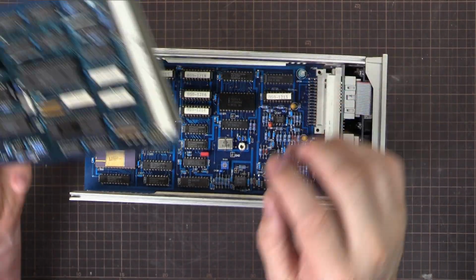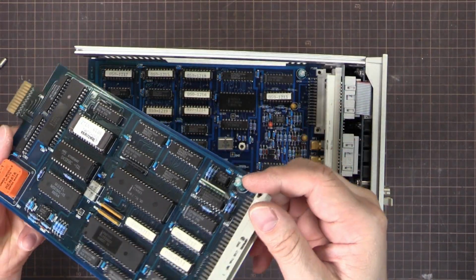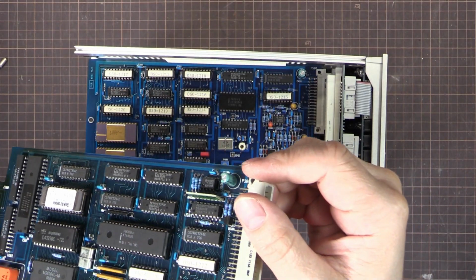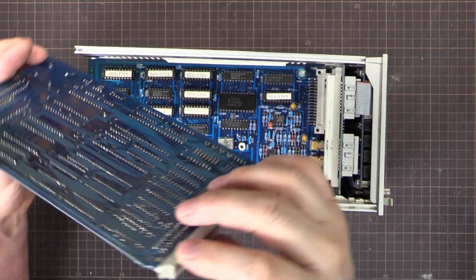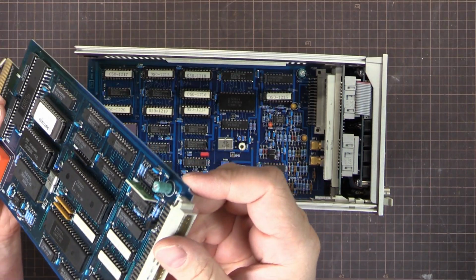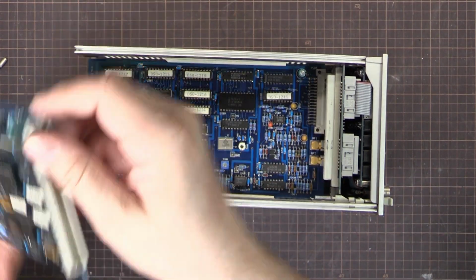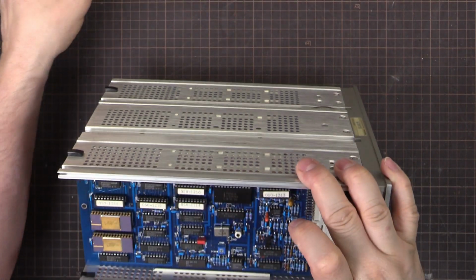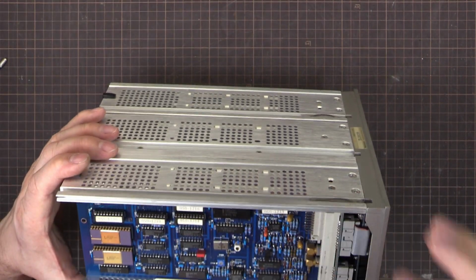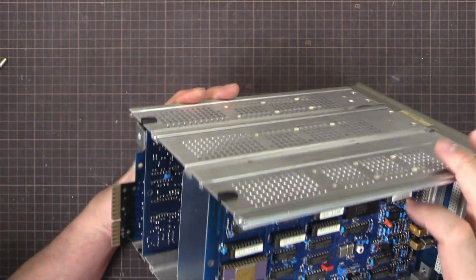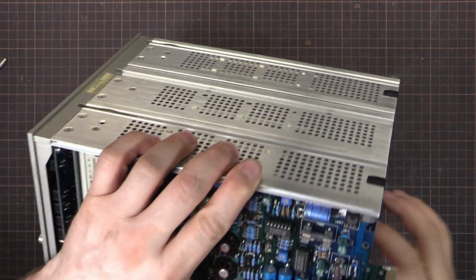There's the electrolytic here. What's that? What brand is that? Towa brand, Towa. Never heard of them. 105. No, that's 85 degrees rated. So maybe I'll pull 1 or 2 and just check it, because I don't want to just go and shotgun all the caps if I don't need to. But they're pretty cheap anyway, so maybe not.